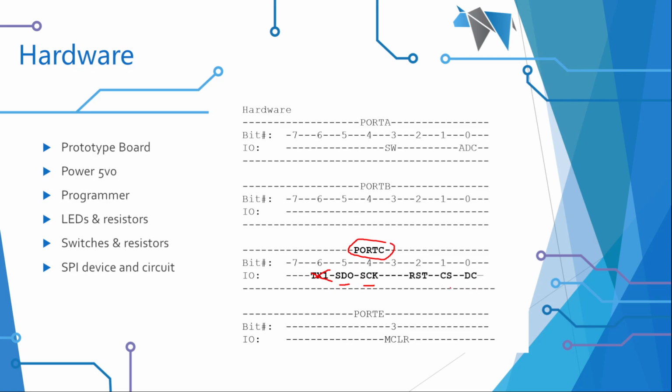And then I've got this chip select or CS line, but this requires two more. It requires a reset line, and that's something on the hardware itself. And whether you are sending a data packet or a command packet, and it's called the DC line. So you've clearly got 5 connections to this GLCD. You might only have 3. You might not have a reset line or data control line when you use a memory device. But typically you're going to have 5.